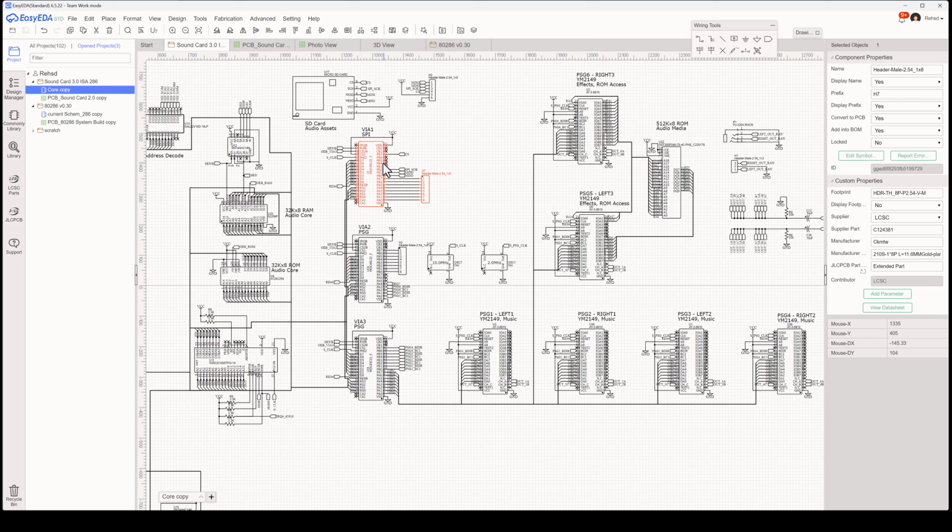Now, I could debug through SPI, so I could send logging out of SPI. That's a fair argument. But I want to be able to plug an LCD in, and so I have a standard 1602 2-line LCD that I can completely manage off of a single port using, I believe they call it nibble mode, where instead of sending it 8 bits of data, I can send 4 at a time and still control all the other signals on that LCD.